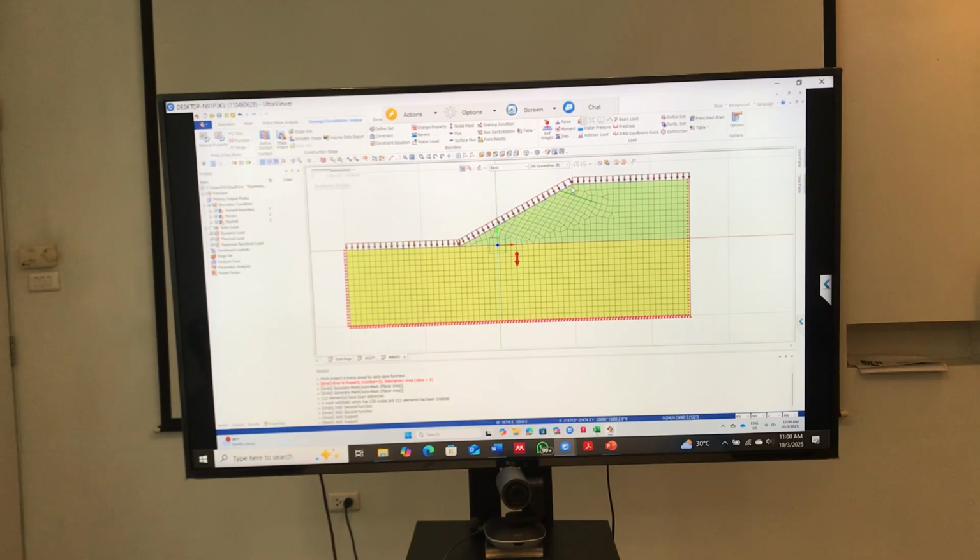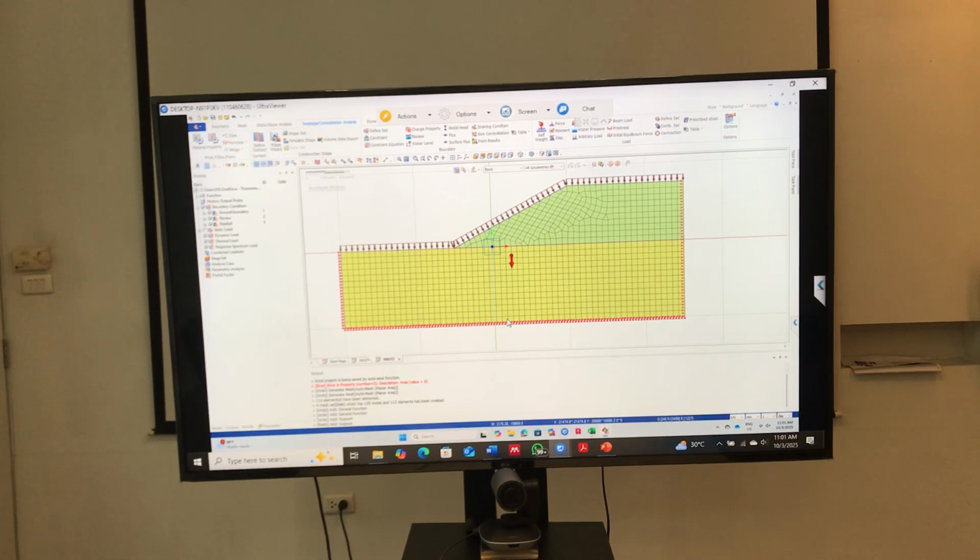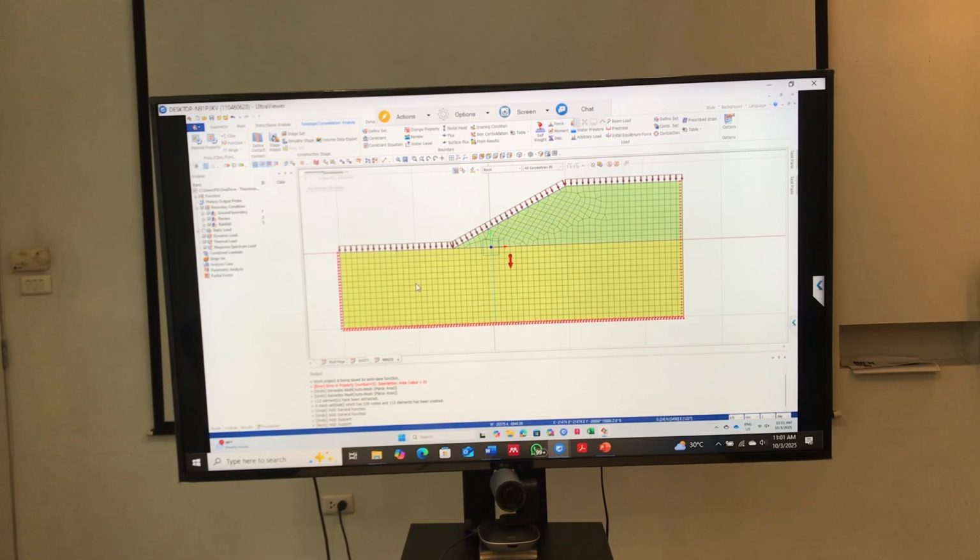So this is how it is. But it affects the result if we don't do that in the bottom boundary, right? Because the water is just flowing, the consolidation settlement will be significantly more than under normal conditions, assuming the soil is porous and not clay. Maybe we can define another material at the bottom, like rock. We put a rock. Maybe if it's clay, but still if it's also clay, the water will not even be moving very fast.